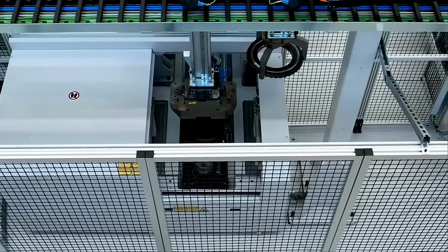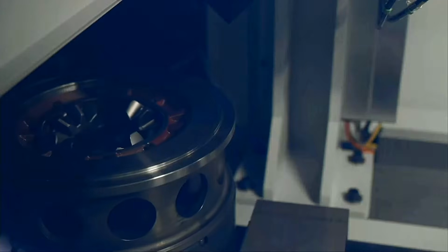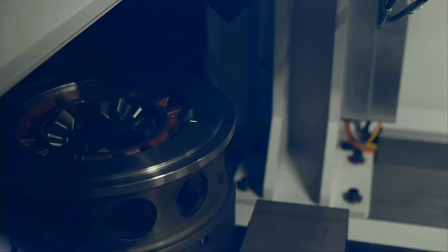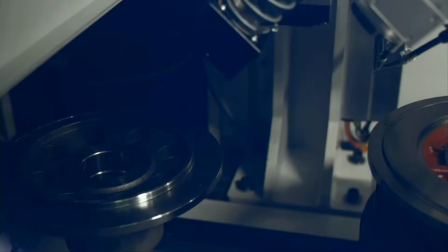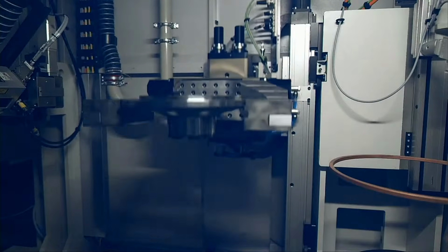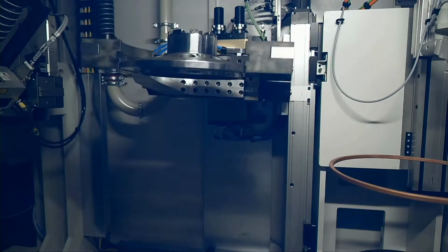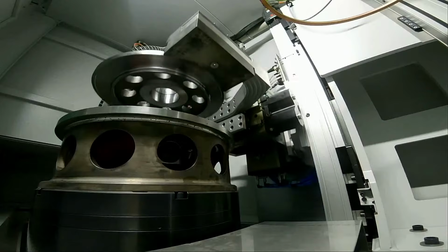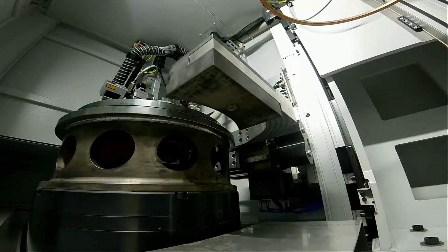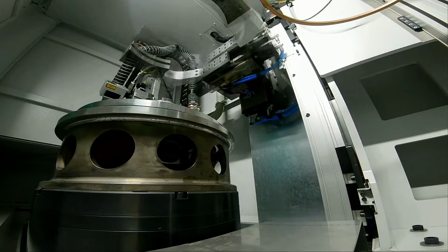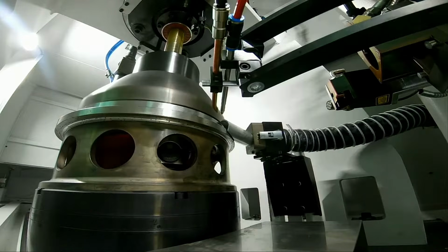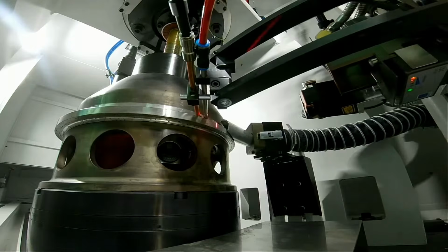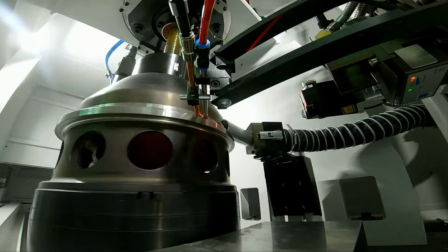So we now start by picking up the first two single components, loading them into the welding machine, and then we start with the cleaning operation. As I mentioned, it's a very short cut. First we start with the laser cleaning operation of both workpieces. Then we have a 180 degrees turning operation implemented in the machine to bring them into the right position to weld them. Afterwards we press the parts together up to 100 kilonewton. Then we start with the seam detection and then directly with the welding operation.